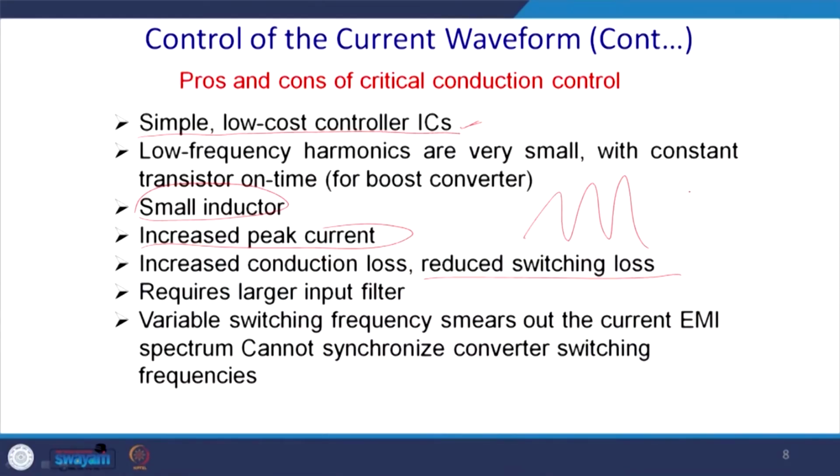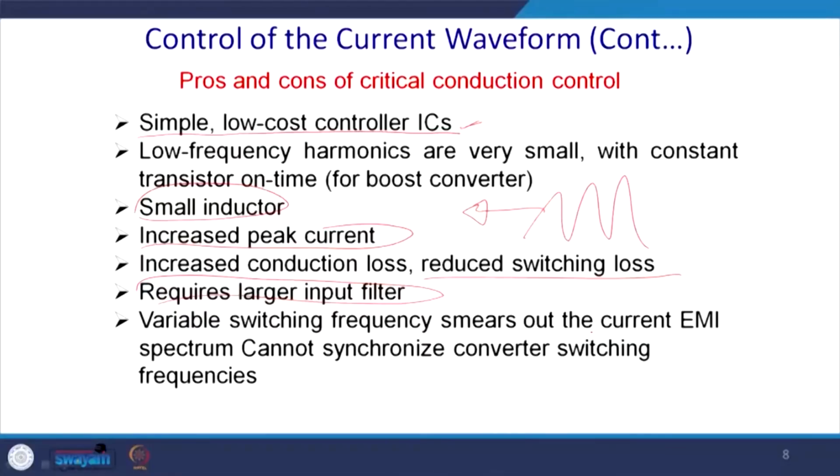However, this requires larger input filters, because this will be reflected on the AC side. AC is your input, and thus it has to be made sinusoidal, and thus you require a large input filter, and thereafter the variable switching frequency smears out the EMI current.